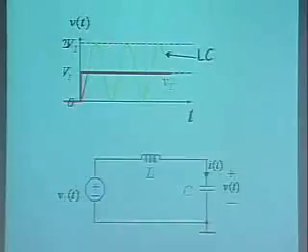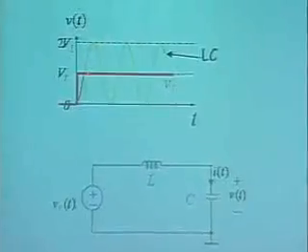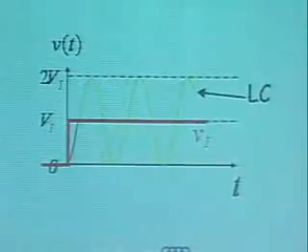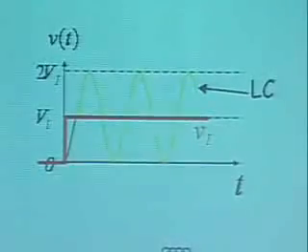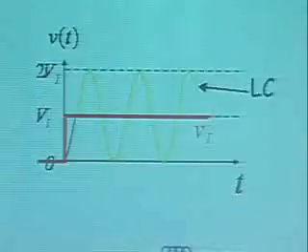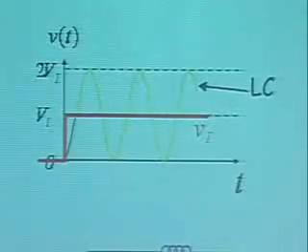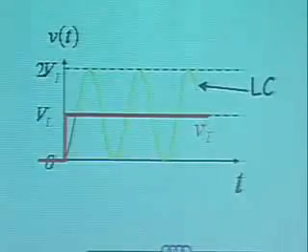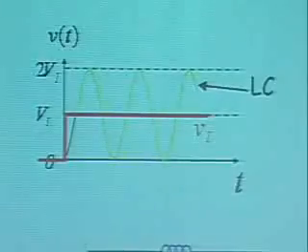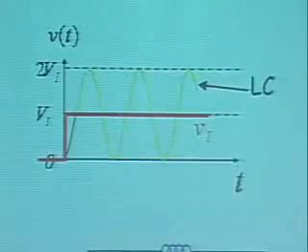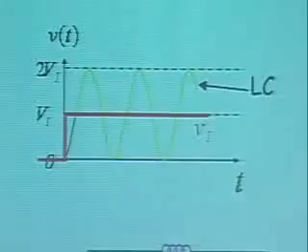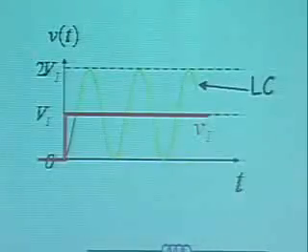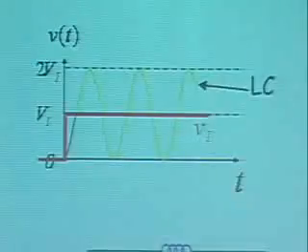By the way, the fact that the capacitor voltage shoots above the input voltage is actually a very important property. We won't dwell on it in 6.002, but just squirrel that away in your brain somewhere. I promise you, sometime in your life, you will have to create a little design that will need a higher voltage than your DC input. And you can use this primitive fact to actually produce a DC voltage higher than you're given, and then use that somehow.